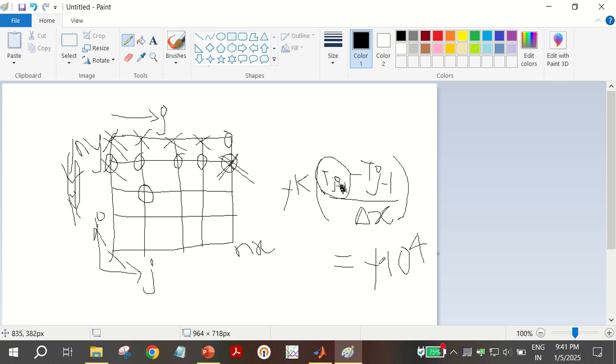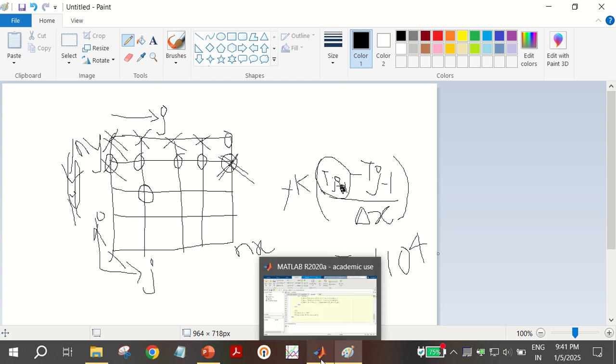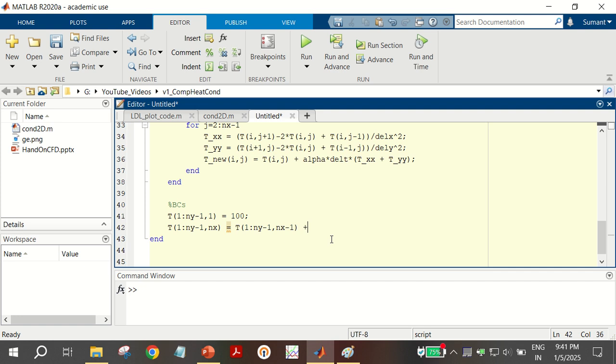So what will it be then? This going to the right hand side, it will be 10 power 4 divided by k, right? So that's the way. k into dt by dx. Sorry, I missed del x by k. So T minus this T divided by del x, into k, it should be equal to q.